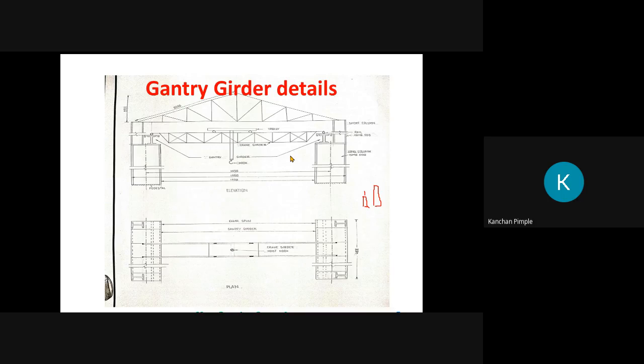So you have to show the equidistance, the point at which the maximum bending moment is there. And again, how to calculate maximum shear force in gantry girder. In that case, what is the location of the crane girder? So you have to remember the wheel should be at the support. Then we get maximum shear force. Okay, so just remember this bit.